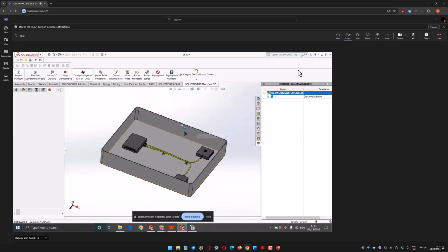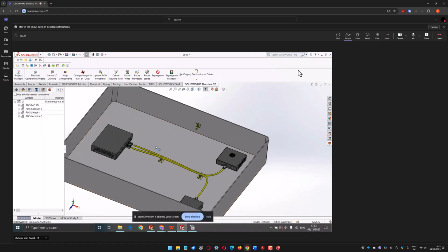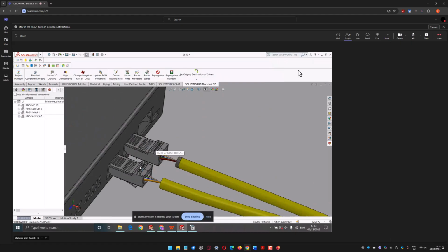section here, and this tab will appear in your SolidWorks 3D, and you can just right click here and then start searching for your project, and then once it's open, you just double click your main assembly, your electrical closet assembly, and then start populating your connectors to its respective position.